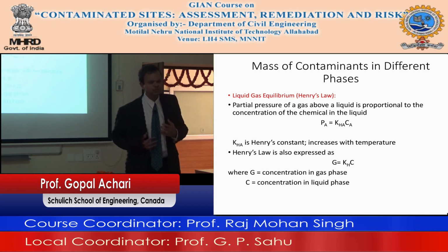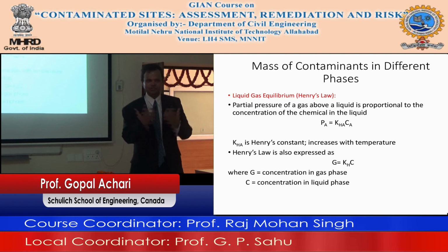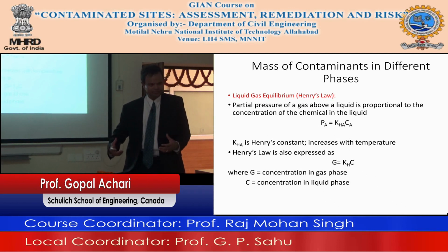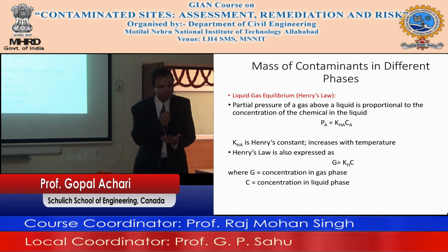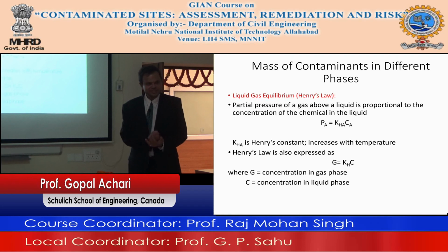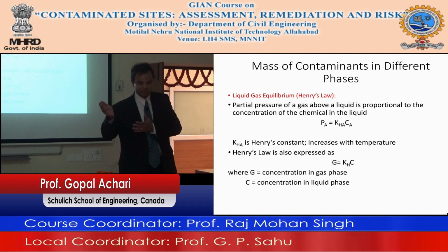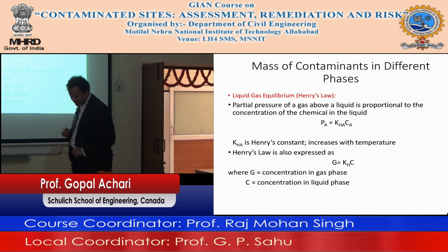So the moment you start putting a system in place to remediate, what is going to happen? Let's say you are doing vapor extraction. You are extracting all the vapors out. What's going to happen? All the clean air from the side will come in. Okay? And you will get the vapor out. But what will happen to the pore liquid that is present in the dissolved phase? There will be a lot more that will start to move into the vapor phase. Okay, let me back up here. I think this requires a little bit more explanation.